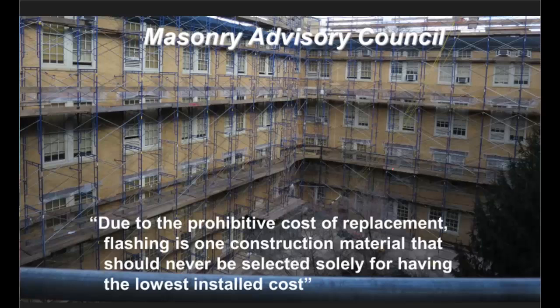That's at ground level. So imagine buildings that are 5, 10, 15 stories high. To replace flashing, you're putting scaffolding up, and you're tearing away the wall. You're taking everything out. You're putting everything back, the insulation, reintegrating it with the air barrier. It's a very labor-intensive process.